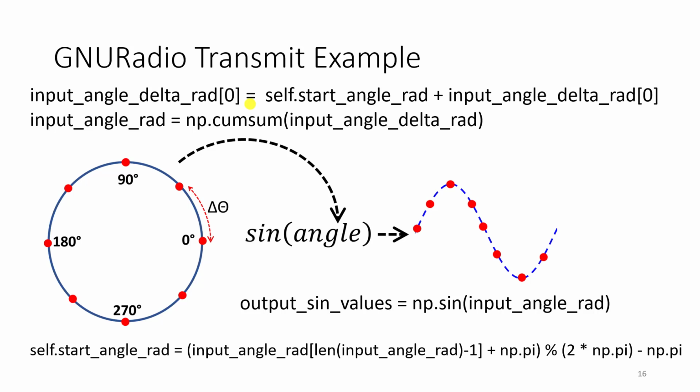And the way we're going to demonstrate this is the use of GNU Radio in the Python programming language, and I'll show you the code, but just to highlight, there's a couple key lines that you want to look for, and these key lines are indicated, these two and then these two down here. And basically this is actually an array. It looks like one element of an array, but what's contained in this 0th element is an array. And this array represents a step size of that line that we showed,